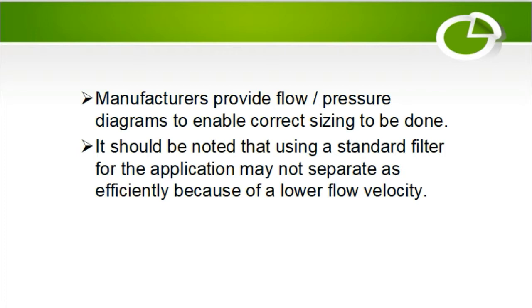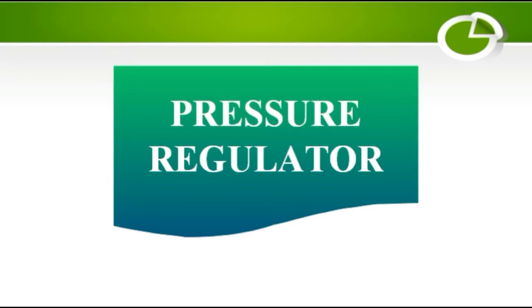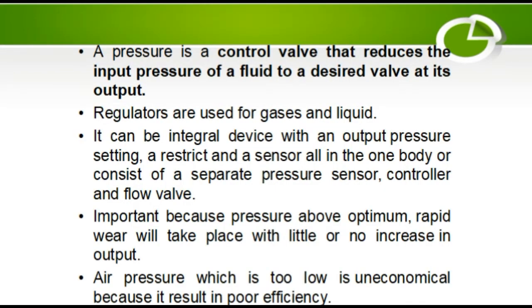It should be noted that using a standard filter for the application may not be separated as efficiently because of a lower flow velocity. Pressure regulator. A pressure regulator is a control valve that reduces the input pressure of a fluid to a desired value at its output. Regulators are used for gases and liquid.